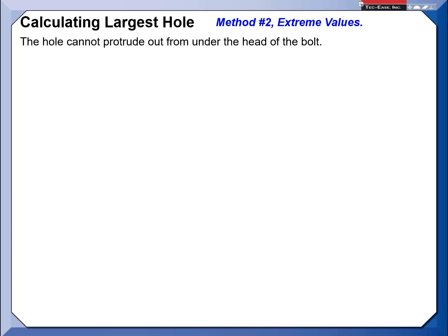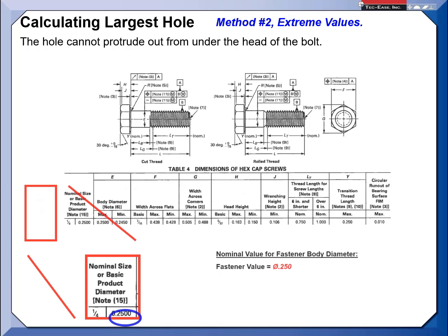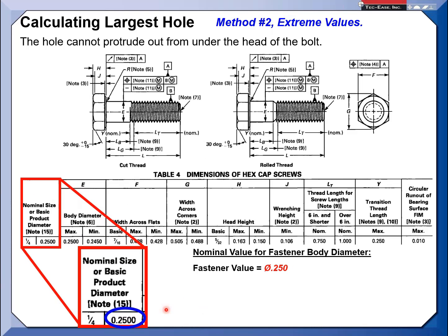So I was just showing engineering that there's more than one way than using the crutch of the plus-minus default tolerance or holding very tight tolerance. Now, if the hole's a key locator, yeah, you may want it really tight, but I'm just going the other way. So now the extreme values. Originally, remember, for the fastener size we just left it basic, and it was a quarter-20 bolt. Well, now we've got to derive what could be the smallest bolt, the LMC size.